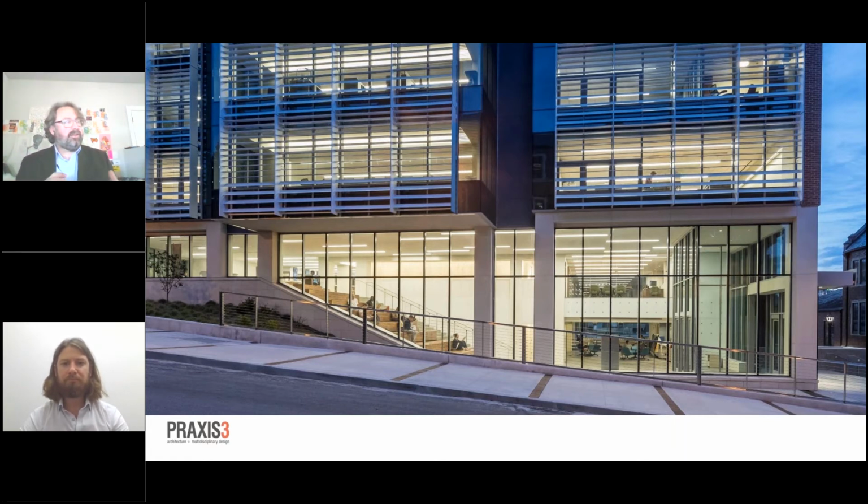We created these optimized sunshades that allow people to see through in the zone that corresponds to where most of our eyes are. And the angle of the louvers is different in other places to create maximum shading for the glass and also to reflect light back up to the ceiling at the interior of the space to increase the daylighting profile. So we really focused on those and kind of left the brick alone. It's kind of the lesson we learned on that project.